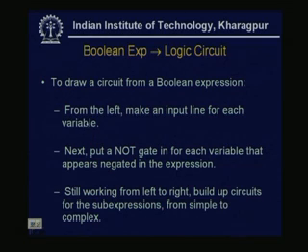From the left, make an input line for each variable. Next, put a NOT gate in for each variable that appears negated in the expression. Still working from left to right, build up circuits for the subexpressions from simple to complex.